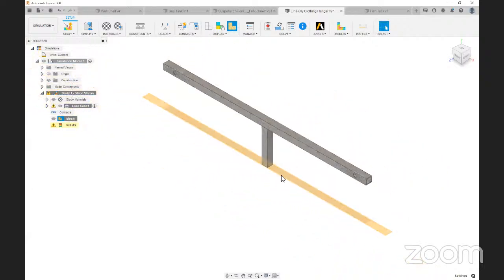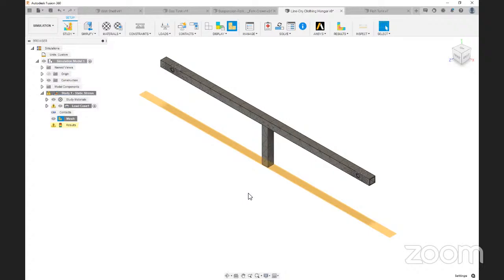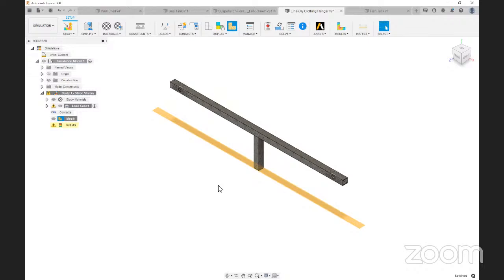We don't need an extra 8 times 50, 400, 4,000, whatever, triangles down below here to worry about. We'll just focus on what we're solving for, which is why best practice is to remove that with a split body command or whatever scenario you have.